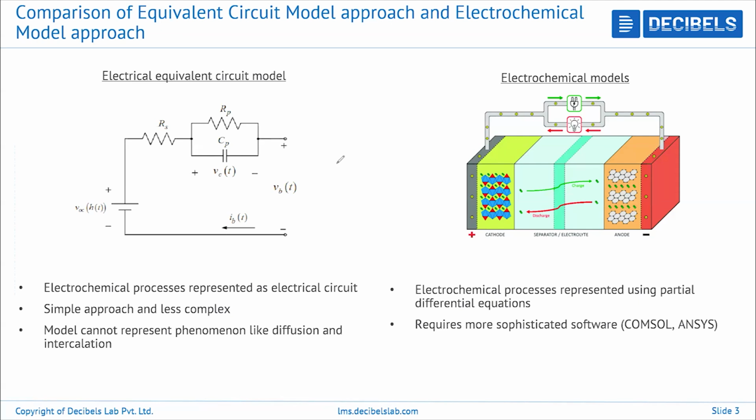But since you can't represent them so easily in electrical terms, we usually simplify it down completely into two simple parts, that is a parallel resistor and capacitor. So this entire equivalent circuit concept is built on the theory of Thevenin's theorem. If you have studied a bit of electrical engineering, you will see that Thevenin's theorem talks about simplifying complex electrical circuits into simple electrical circuits. So that's the concept of the electrical equivalent circuit model.